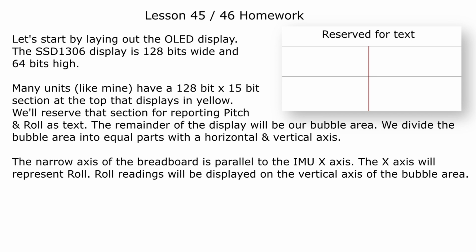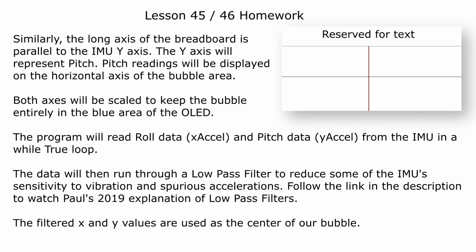The narrow axis of the breadboard is parallel to the IMU x-axis. The x-axis will represent roll. Roll readings will be displayed on the vertical axis of the bubble area. Similarly, the long axis of the breadboard is parallel to the IMU y-axis. The y-axis will represent pitch. Pitch readings will be displayed on the horizontal axis of the bubble area. Both axes will be scaled to keep the bubble entirely in the blue area of the OLED.